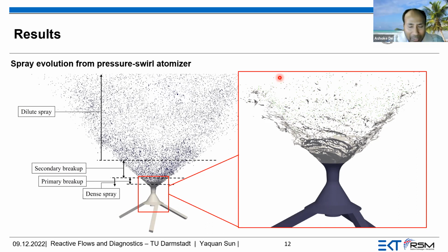Okay. Now you said you are planning to couple with the combustion. Here you want to do it with the Eulerian stochastic field, right? I'll go back to my question from the earlier session this morning. So the Eulerian stochastic field, will this be active both in the Eulerian phase and the Lagrangian phase? Or in the Eulerian phase you only consider the evaporation, and then when the particle gets converted, only then you consider the combustion. How would you like to approach that? The question is how I would like to.